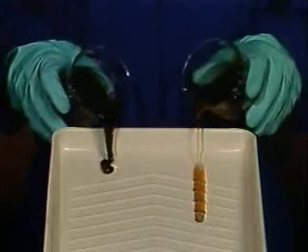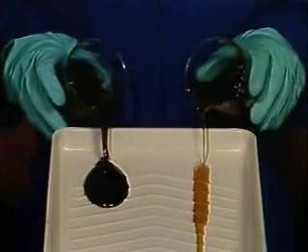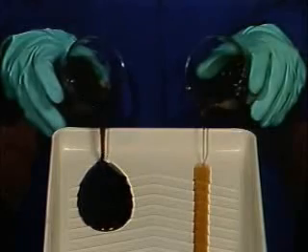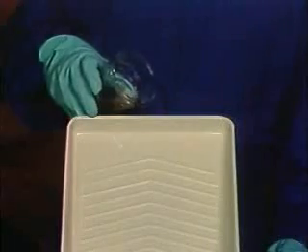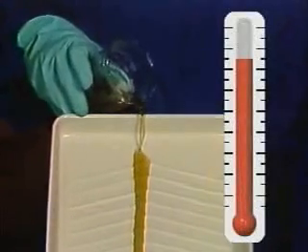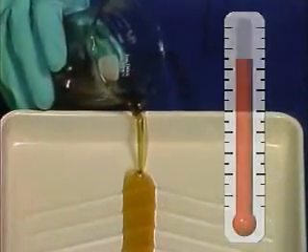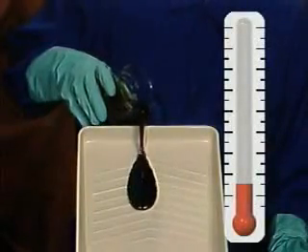The thicker lubricant has a greater resistance to flow, so it has a higher viscosity, while the thinner lubricant has less resistance to flow and therefore a relatively low viscosity. The thinner the lubricant, the lower the viscosity. Viscosity is affected by temperature. Higher temperatures cause lower viscosity because lubricants thin as temperature increases. On the other hand, lubricants thicken as temperature decreases. Both cases are significant because a lubricant won't lubricate properly if it's either too thick or too thin.